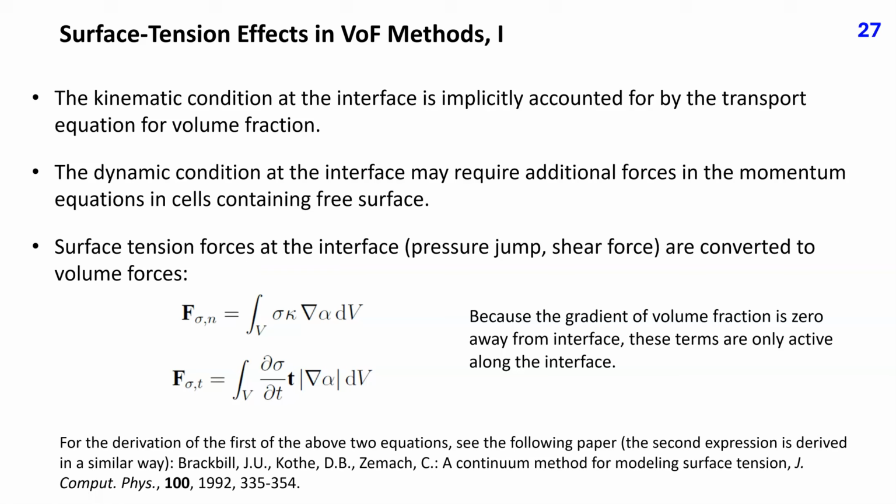The so-called parasitic currents can develop if the fluid moves only slowly or not at all, and the surface tension effects dominate, that is, with a high free surface curvature or surface tension coefficient. This is manifested by high velocities with erratic directions in the vicinity of the free surface, which can cause numerical problems.